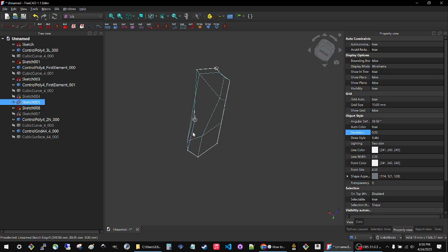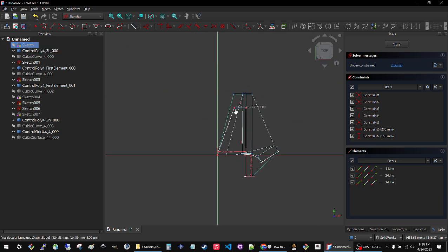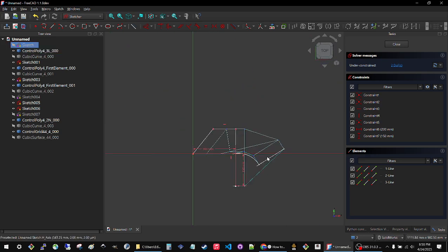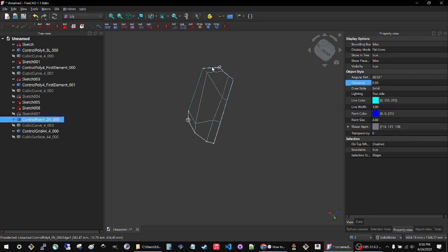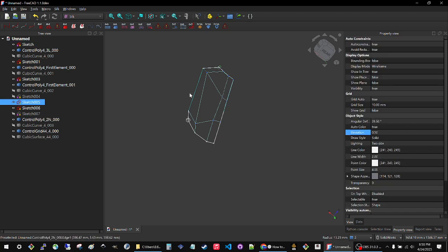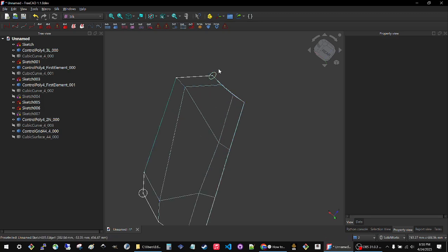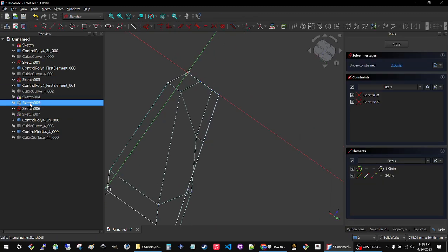the program. So you can just come back to the sketches, bring them back to being a little bit more normal, a little bit more reasonable. And normal and reasonable means that this grid is not too distorted. So here we have a lot of distortion, like really long, really short. Let's fix that up again just a little bit. It's one thing that's really nice about the circles: not only do they tell FreeCAD which way to grow the curve, but they also make it really easy to click onto and find the sketches.